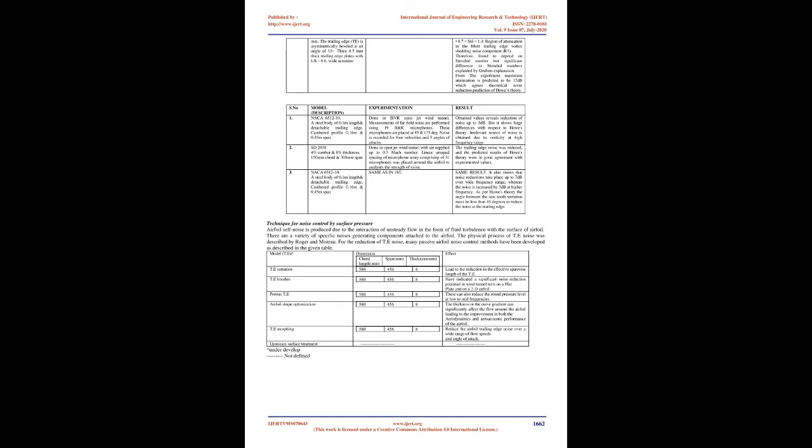The experiment is performed in an anechoic wind tunnel test chamber of 1.4 m x 1.4 m x 1.6 m internal dimensions, and has walls that are acoustically treated with foam wedges to approximate a free environment at frequencies above 250 Hz. The facility contains a contraction outlet that is rectangular in cross-section with dimensions of 75 mm x 275 mm. Acoustic measurements were recorded at a single observer location using a B&K 1/2 inch microphone located 554 mm directly below the trailing edge of the reference plate.